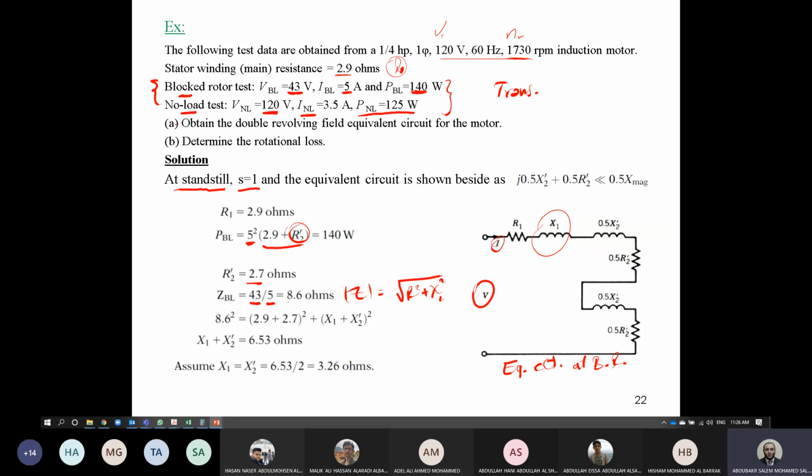But in the DC motor we did not make a blocked rotor test in order to obtain the parameters. In the DC motor we made an acceleration test and a time constant test. We made many tests in order to obtain the motor parameters. But here for AC machines we need only 2 different tests, besides getting the resistance using an ohmmeter. These tests are the short circuit or blocked rotor test, and the no load or open circuit test.